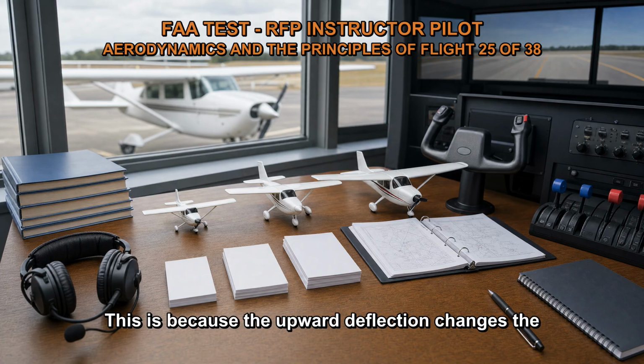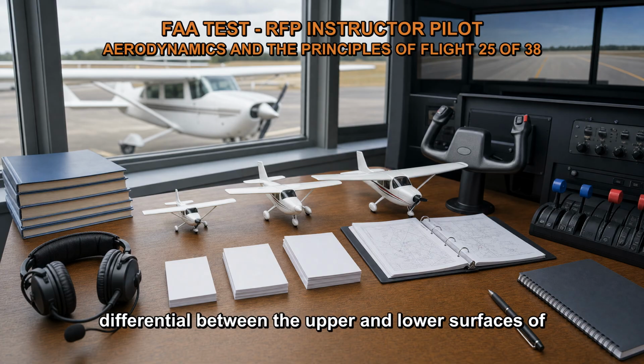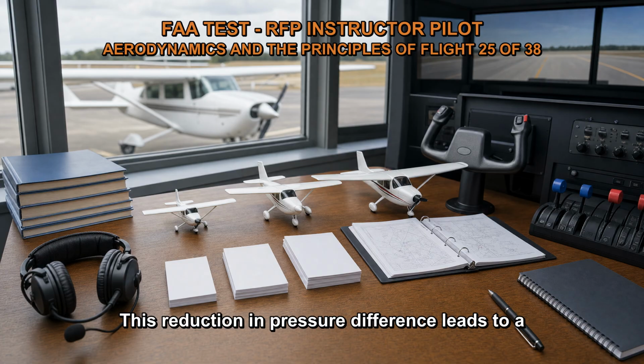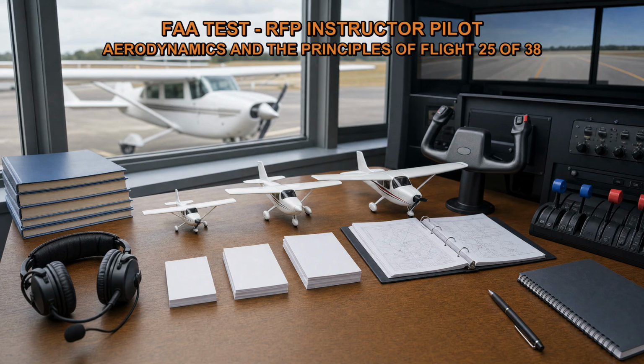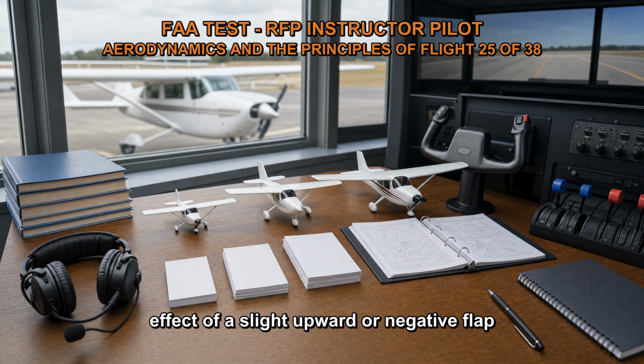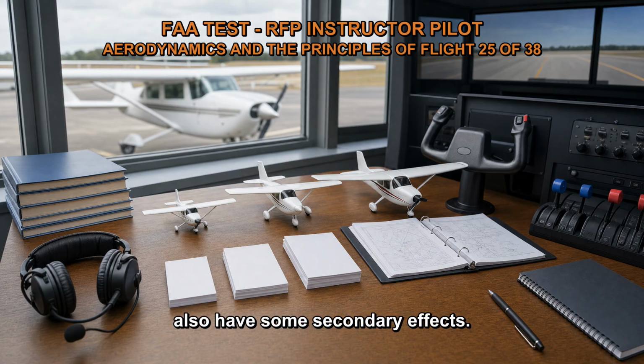This is because the upward deflection changes the airflow pattern over the wing, reducing the pressure differential between the upper and lower surfaces of the wing. This reduction in pressure difference leads to a decrease in the aerodynamic drag experienced by the aircraft. While the decrease in drag is the main effect of a slight upward or negative flap deflection, it's important to note that it may also have some secondary effects.